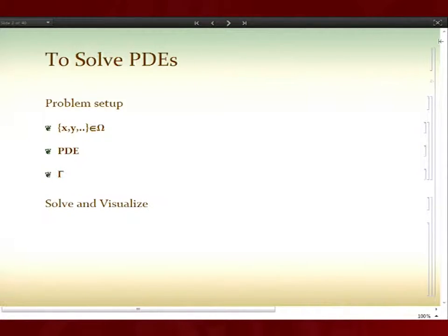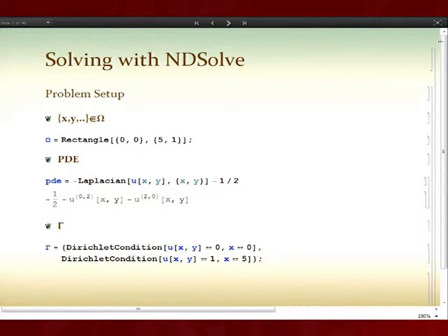You need to specify a region, PDE, and boundary conditions. Solve and visualize, that's generally the steps you need to take to address a PDE. And you will see that within NDSolve, the steps that I present here are pretty similar. So just for a quick recap, to see how that actually looks within NDSolve, I've specified a rectangle. The PDE is a Laplacian. One thing maybe to note is that for the PDE, this coefficient here is -1 and -1/2. We'll see those a bit later.